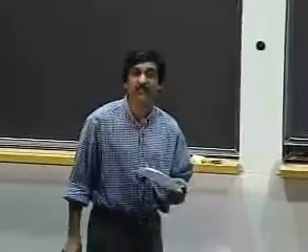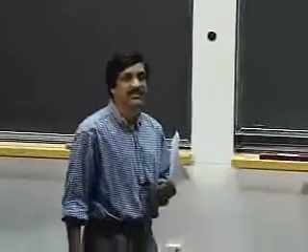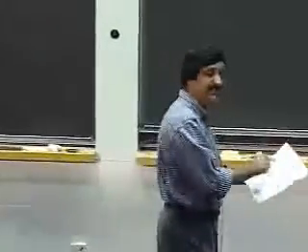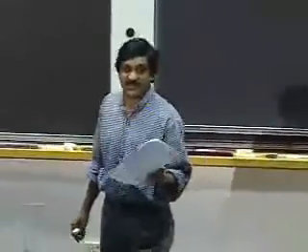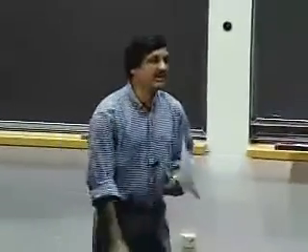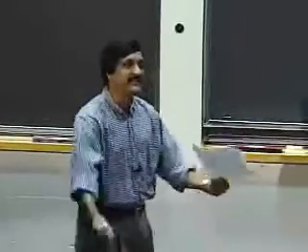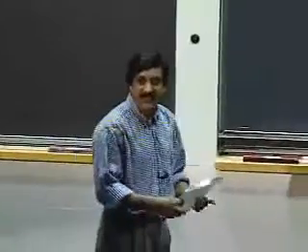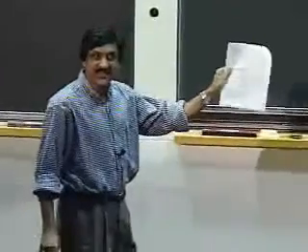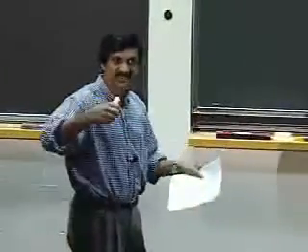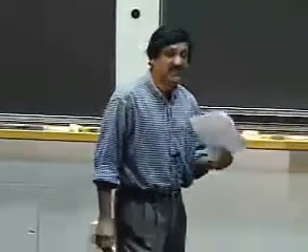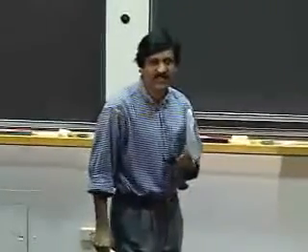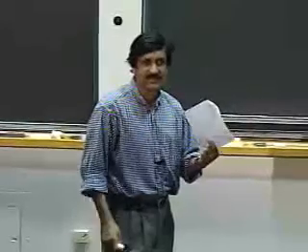So I've circled 2 things on page 2. One thing that I've circled is the power supply range of 0.7 to 1.3 volts. Notice that the power supply voltage for these chips is significantly lower than the 5 volts that we've been nominally talking about in this course. When in doubt, our problems have used 5 volts. But notice that in this technology, they're talking about using voltages for the power supply, VS, in the range of 0.7 to 1.3. So why is it so much lower? Well, we'll find out.